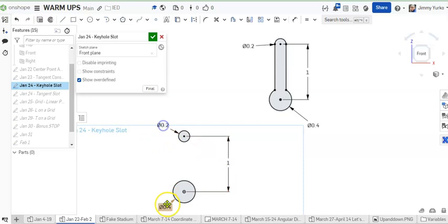Now it's just a matter of putting the vertical sidebars in, and that's the line tool, which we can get from the tool ribbon up top or by tapping the L key on the keyboard. We can draw two line segments by clicking and releasing, moving the mouse vertically, and then I'm going to use 2 clicks to end the line segment. I'm done with that, so I'll hit the escape key to put my tool down.